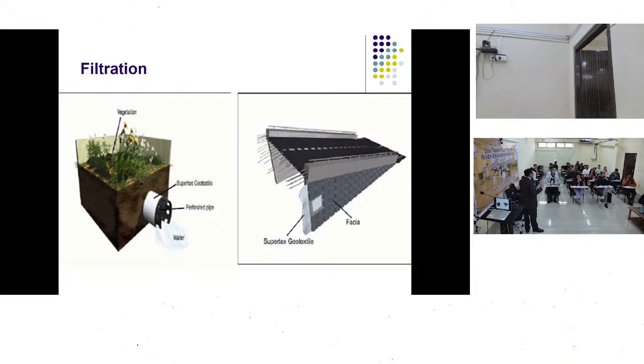So this means if I am going to construct an embankment fill, it should always be drained. It should be in a drained condition. That is why we are providing weep holes. You will see that all along the hill slopes, we install weep holes so that in case there is some ingress of water due to rainfall, that water gets removed through the weep holes.